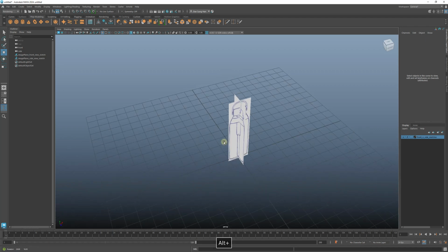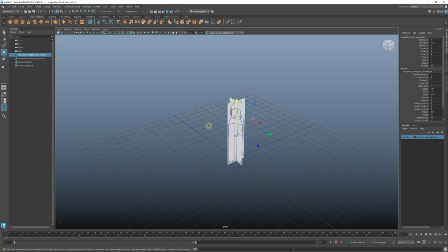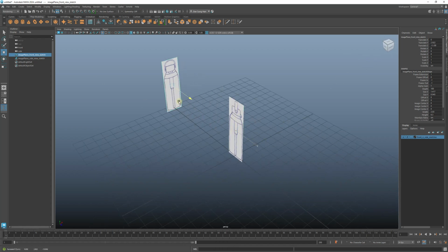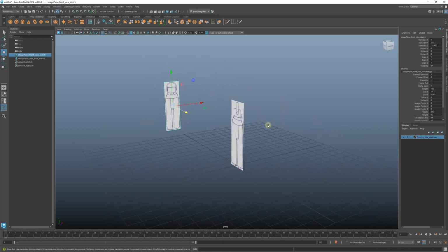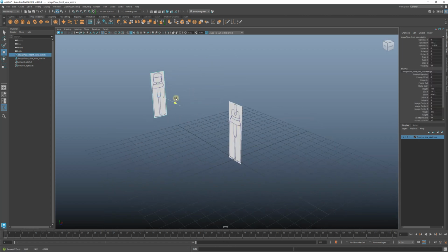Alright, then I'm gonna grab my front view, and there's my front view compass. I'm gonna push it back in space. Several students did not do this. It needs to be done because it's gonna get in the way of your drawing. So I put it back in space using the arrow.